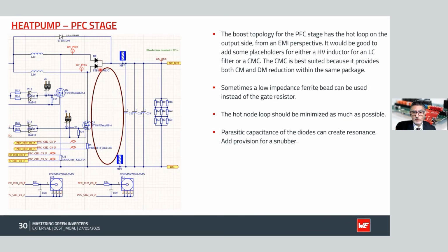Also another thing, and Jakob also mentioned this, the reverse recovery of the diodes at the output. Sometimes we also put a provision for some snubber circuits across that as well.